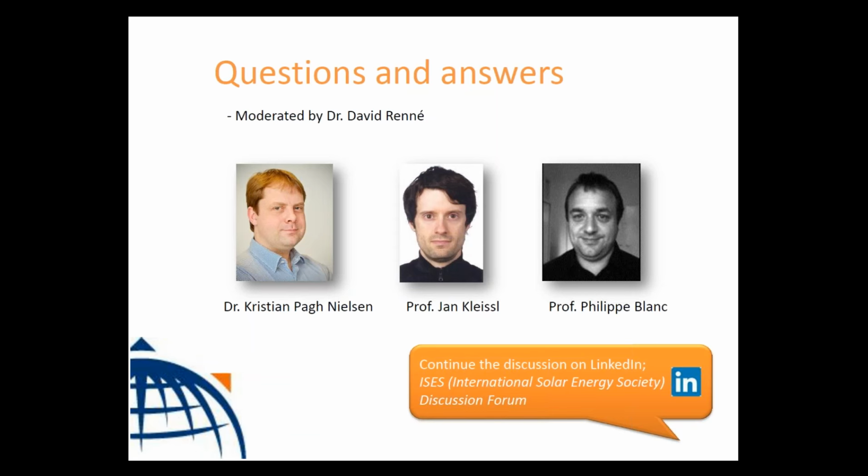From my understanding, the utility is in charge of controlling these inverters, and the PV systems above a certain power rating, maybe 20 kilowatts, which is basically above what these small residential systems are, are required to have this utility control and communications channel,